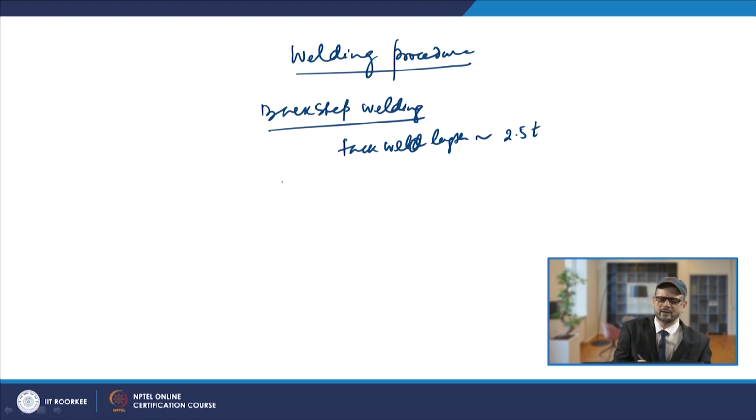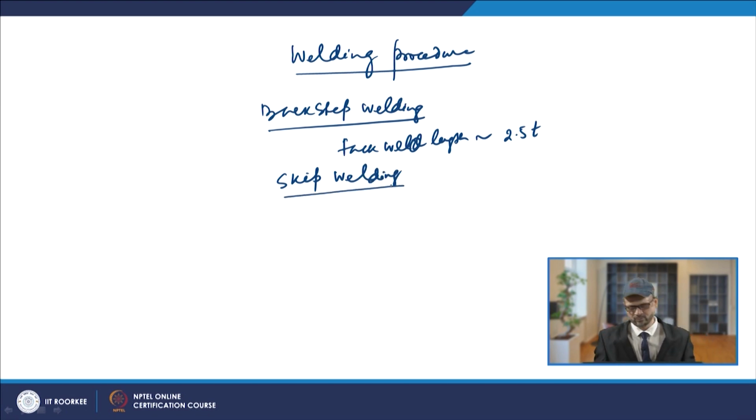Similarly, another method is skip welding, which is another way of reducing the residual stresses. What we do is skip portions: we weld one tack length, then skip the next one and go on to the following.